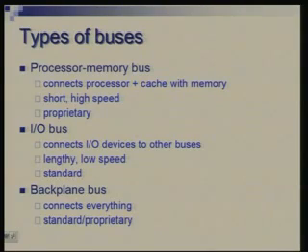Whereas if you are connecting a Sparc processor to the memory, then the whole design will be oriented towards that. This is a proprietary design in the sense that it's not possible to just pick up any arbitrary subsystem and plug into it. Of course, somewhere this would need to be connected to peripherals. So somewhere there has to be a path to the peripherals, but primarily it connects processor and memory.